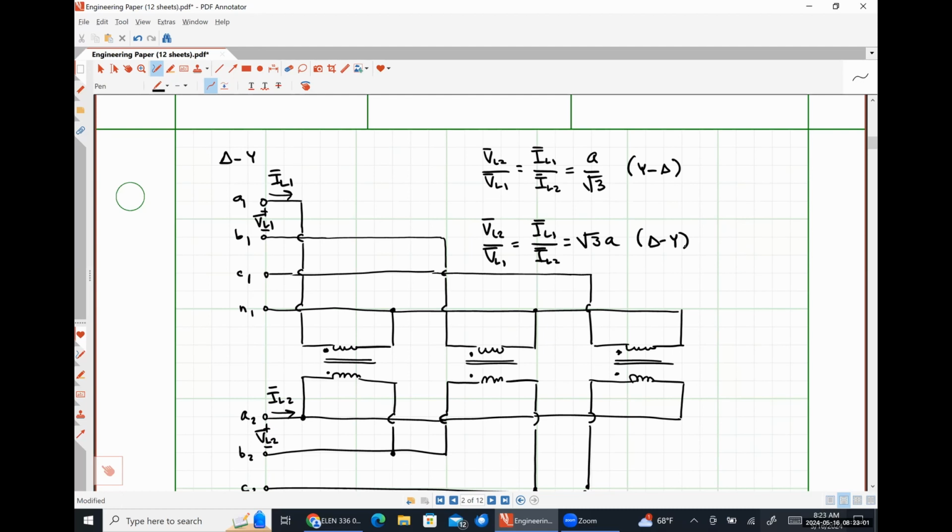Then when the power comes back to the transformer... So you're missing a little something there. A solar panel generates DC power, so your solar panel would actually have to be fed into what's called an inverter, where an inverter is a power electronics circuit that converts DC power into AC power.